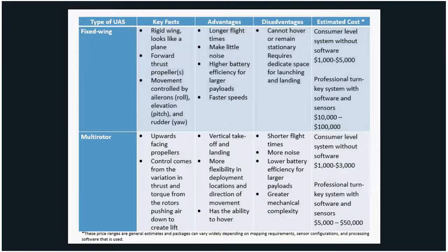Can I quickly jump in on that? This is Sam. Sure, Sam. So certainly if you use an RTK system, which obviously costs a little bit more, but they're coming down in price, we did a comparison with a laser line scan ground survey, and we didn't find any difference in the survey from an RTK system compared to a ground survey of a beach, which I presume would be similar in lacking hills, etc. So I think if you used an RTK system, it would certainly be possible to do an accurate volumetric analysis or something like that.